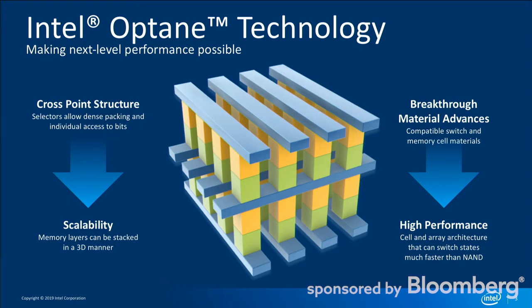So as you add write activity to a NAND drive, you'll see read latency tends to go up. And with Optane drives, read latency remains flat throughout. So not only is it a faster drive, but it also doesn't suffer from write amplification.